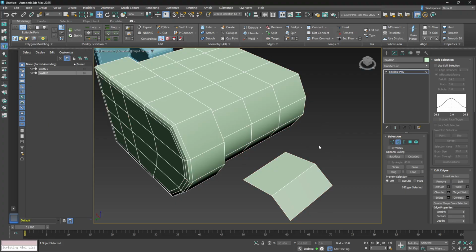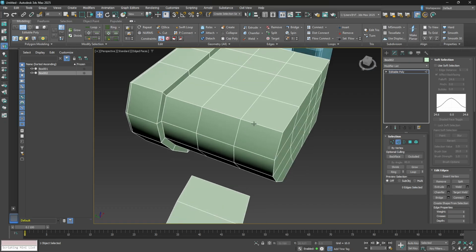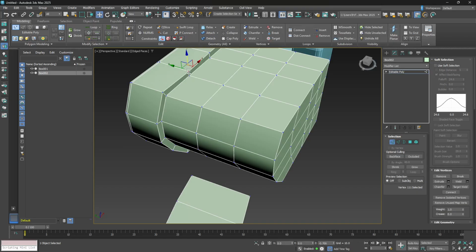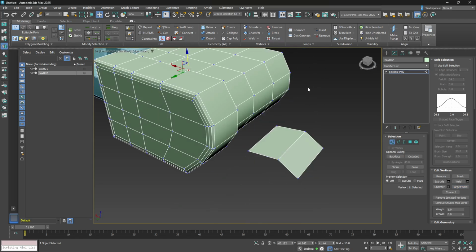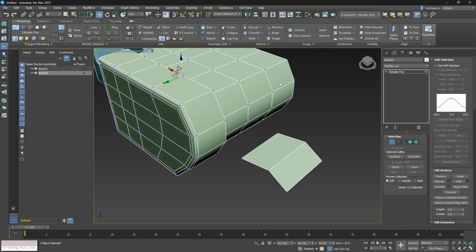One thing that Blender doesn't really do, it can do, but it's a little tricky to set up, is target welding. You have to turn on vertex snap, and then you have to turn on auto merge by distance, and you can start doing target welding basically with snapping. Over here, it's just a button. You select by vertex. You can pull these like one to the other. So turn on target, click, drag, and it's just that fast. It's really that easy. Nothing revolutionary there really, or groundbreaking, I guess.